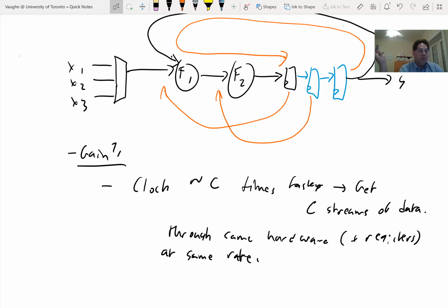And that would be like an extreme example. Once you've basically got nothing but one lookup table or one multiplier in between your registers, adding more registers has diminishing returns. You might be able to get rid of some wiring delay, but after a while, your delays are just the remaining logic that you can't put registers in between. So that could be a single lookup table, a single multiplier or a single RAM block, but you're basically limited by things where you can't get a register in the middle anymore because you're down to kind of indivisible units. And going beyond that's not useful.